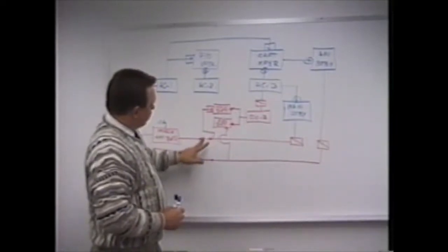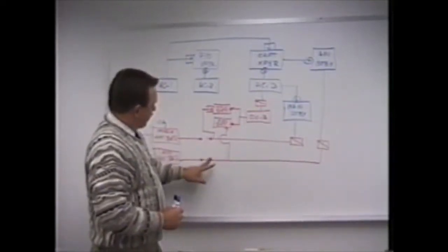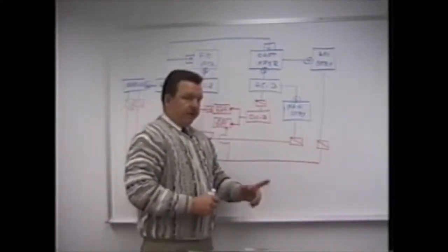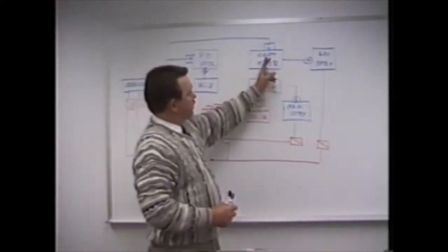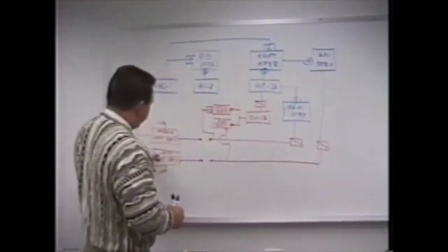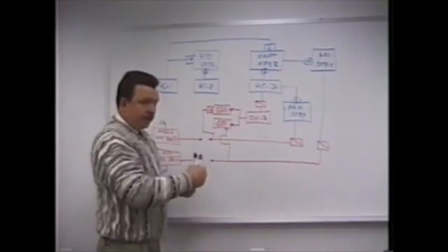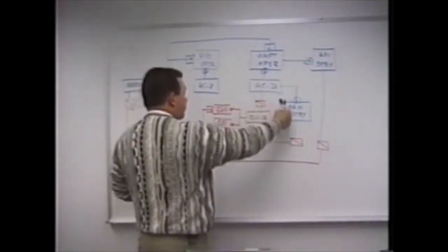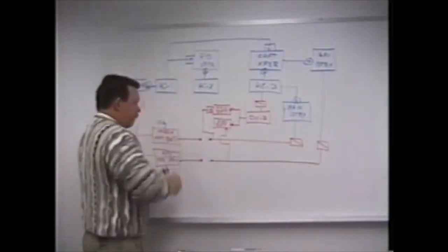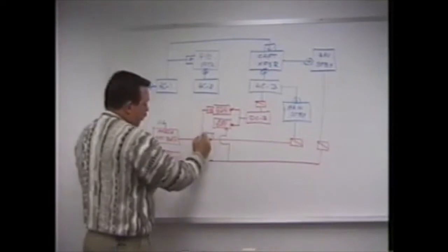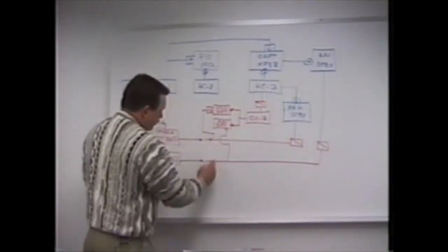In the unlikely event the battery switch was to wind up in the off position for some reason, this would not affect the system. However, if a failure was to occur, such as losing the captain's transfer, APU standby would go looking for the APU hot battery bus, but with the battery switch open, the transfer cannot occur. Likewise, if the main standby was to lose AC bus 3, it would go looking for the main hot battery bus, and the transfer could not occur. So, in normal operations, we keep the battery switch closed.